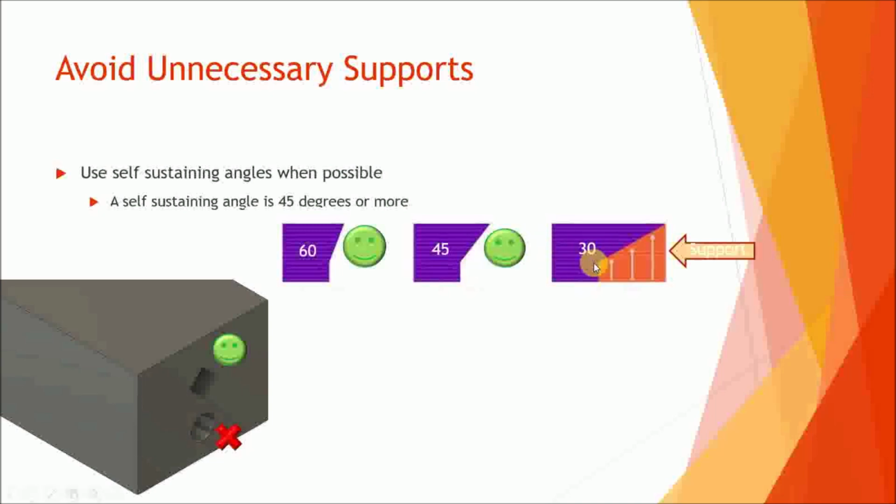So that's what this is. You can see the support material underneath it. If you have dissolvable supports, again, not that big of a deal. The dissolvable support material does cost money, so you are adding cost and complexity to the part, but if that's what you have to do and you can't design around it, it is what it is.